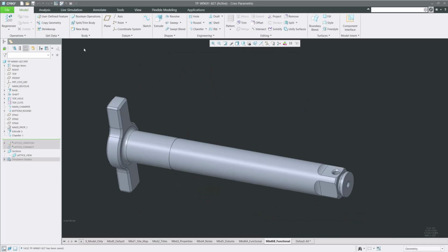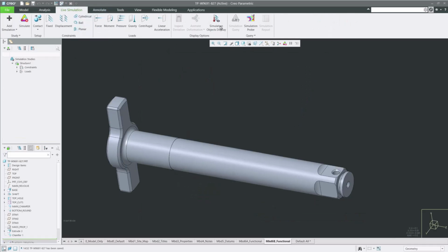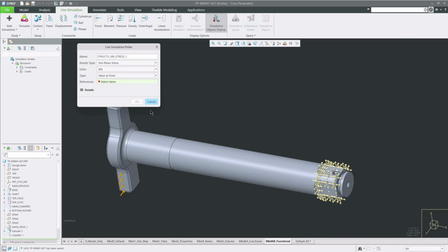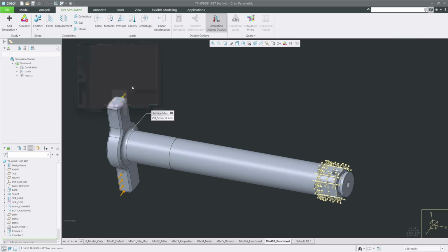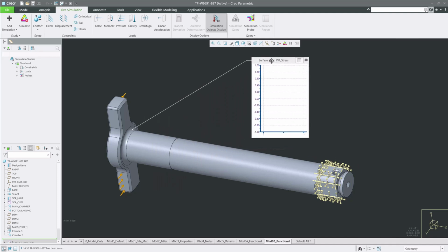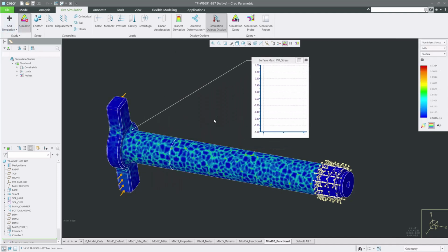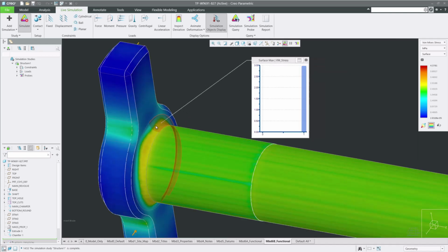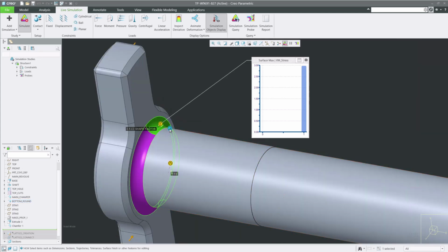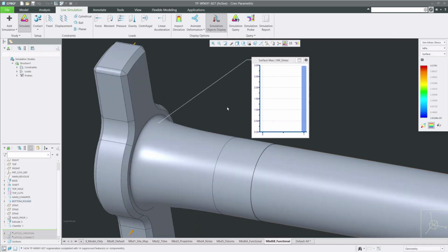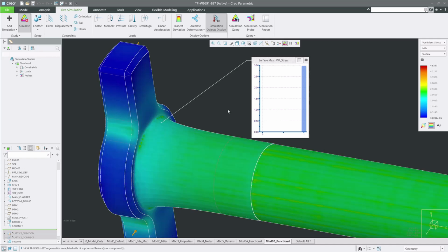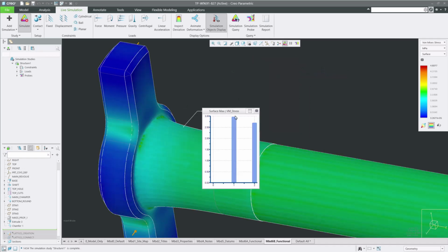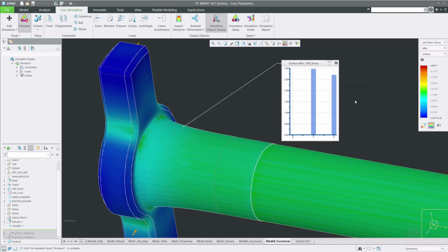Next, let's take a look at one of Creo's 3 built-in simulation engines, Creo Simulation Live. CSL allows the user to run simulations easily during the modeling process and get quick results to inform iterations on the design before it passes to a dedicated simulation engineer, who can perform a more sophisticated simulation using another simulation tool in Creo's toolbox. When we make a change, the simulation automatically runs again, and the new stress values are added to the probe graph, keeping a detailed history of key data values.